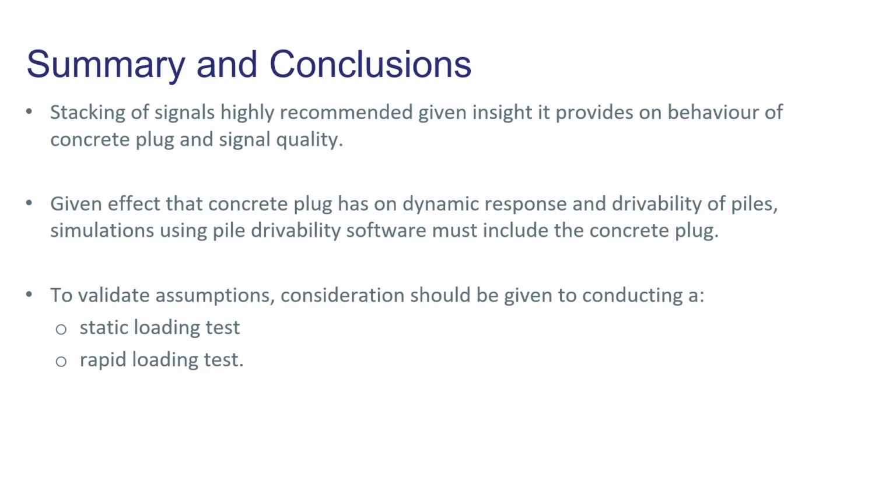Stacking of signals is something that I highly recommend on a lot of jobs, just to get a better insight as to what's going on. It's not that common in the industry. Given the effect that the concrete plug has on the drivability, or the dynamic response and the drivability, we should consider the plug when we're doing our WEAP analyses. And then finally, to validate all these assumptions, it would be great if we had a project where we would be doing a static load test or a rapid load test to actually prove out what I'm trying to say, or what we're trying to say here.